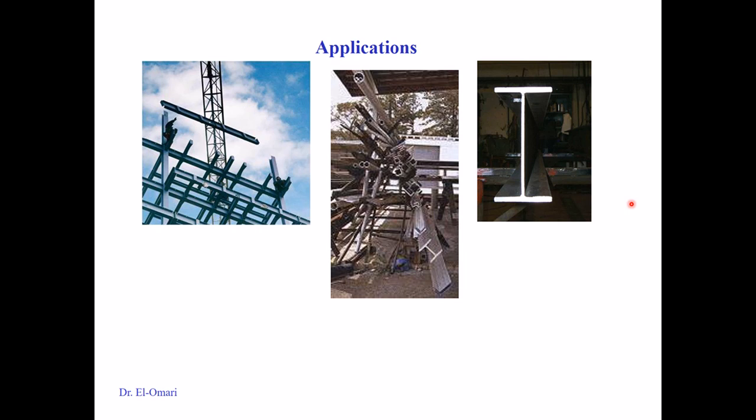Moment of inertia is a cross-sectional property and has nothing to do with the type of material. It is one of the factors that represent how the cross-section would resist rotation. This is what moment of inertia is. In further design classes, you'll learn about other factors that relate to the material, but for now, we just learn about how to find the moment of inertia of a cross-section,